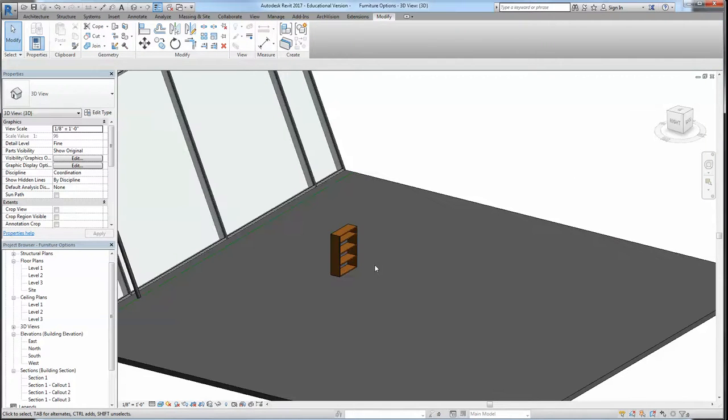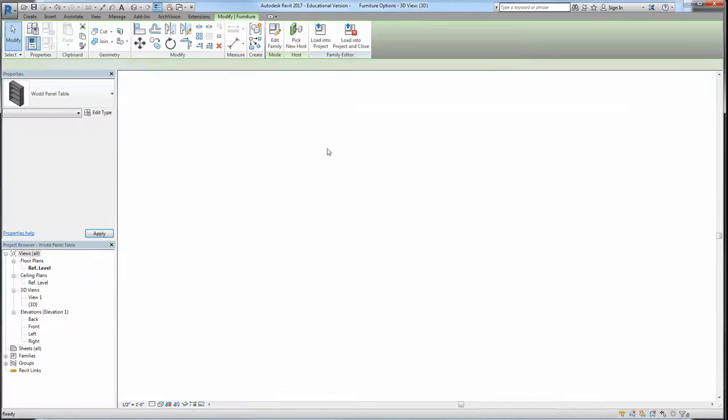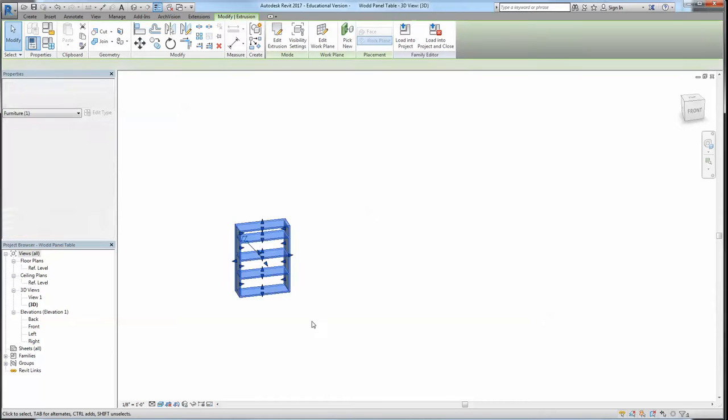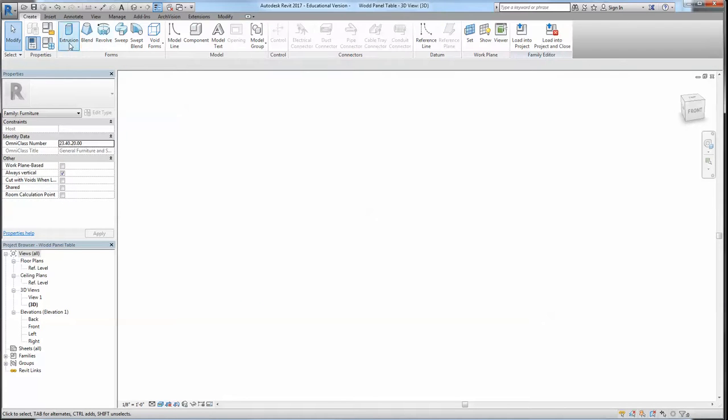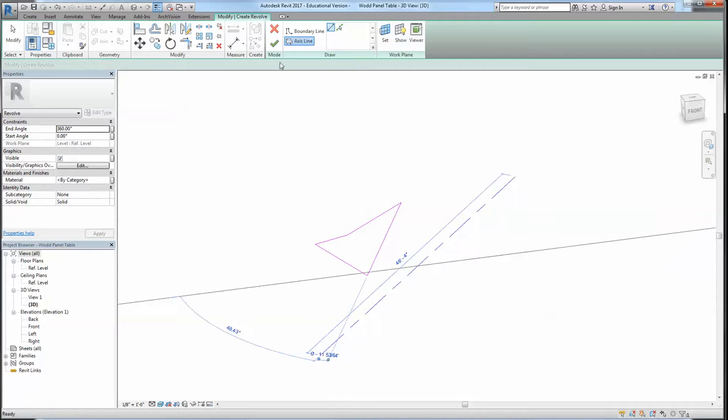Good. So in terms of extrusion, you can do vertical, just because I was doing the drawing from the elevation. You can do horizontal. You can do several components with multiple extrusions, and keep on doing your own system of furniture, for example. If it's a little weird, let's say create a revolve. A revolve is very similar. It pretty much tells you the boundary line and the axis line. So the boundary line has to be a closed element, and then you say give me the axis line, and you create a line here, and then you say I'm done.